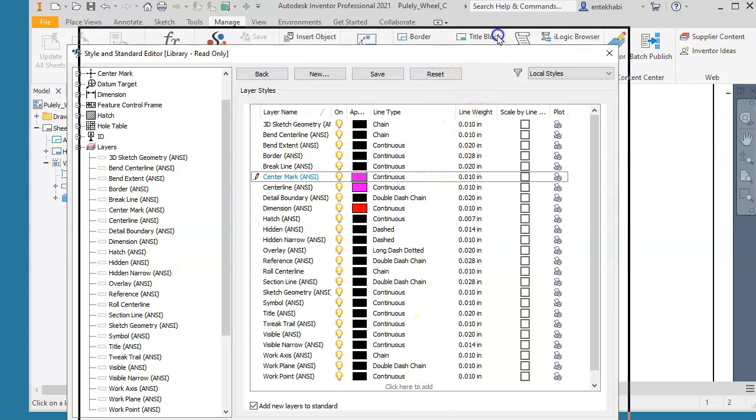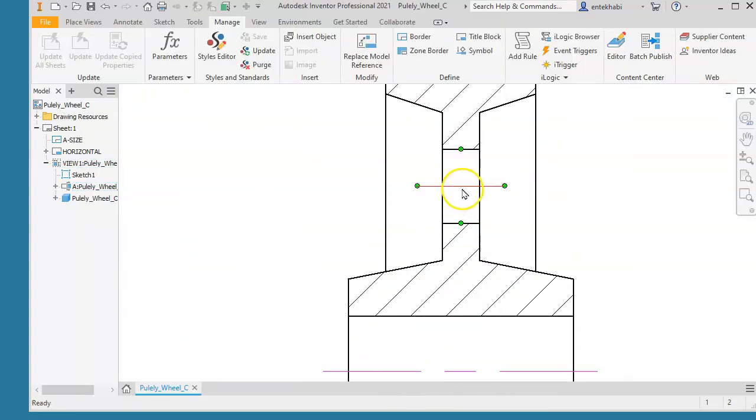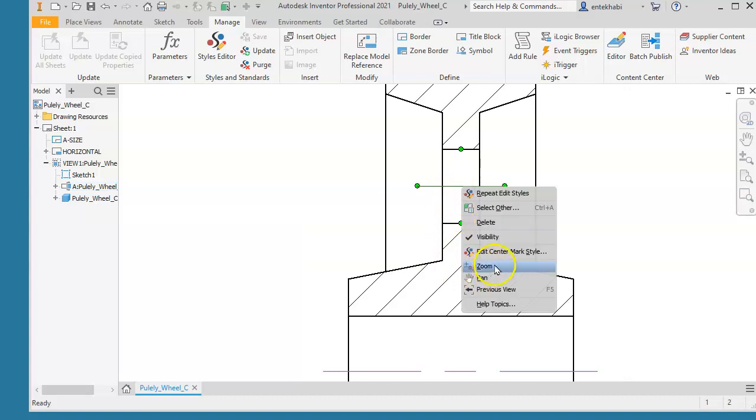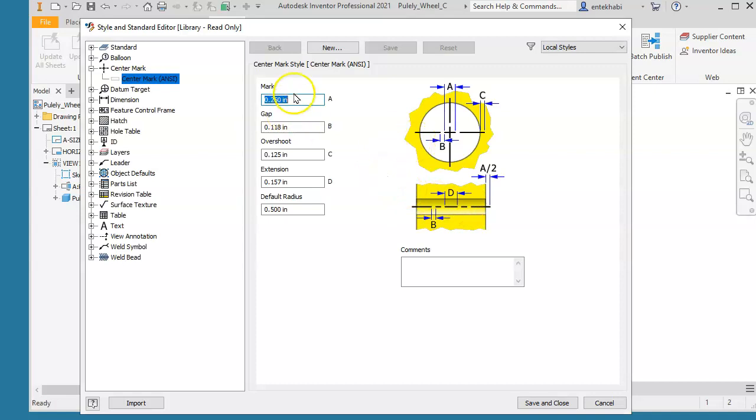And once you do that, the existing one is going to change automatically. And now the center line doesn't show as a center line. As we always do, we just change those settings, divide by 2, all the settings A and B and D. If this does not still change, we can manually expand them or stretch it to make the line type display.